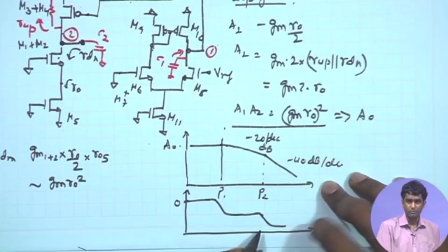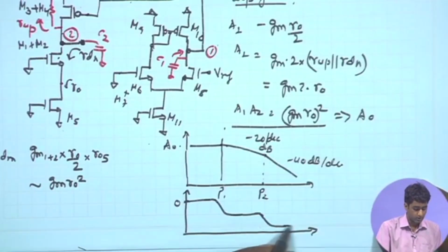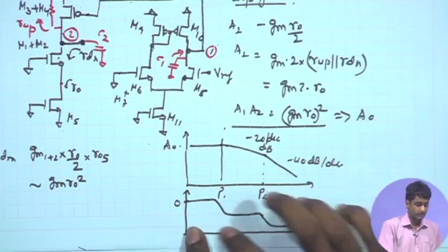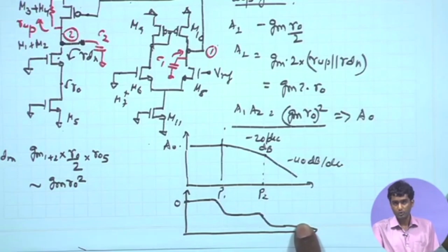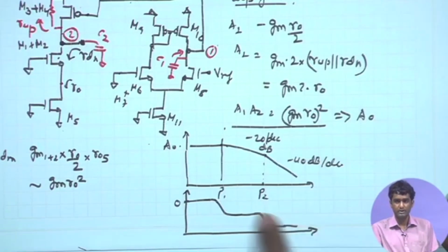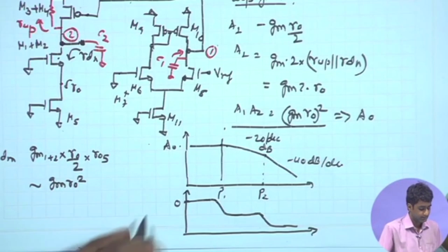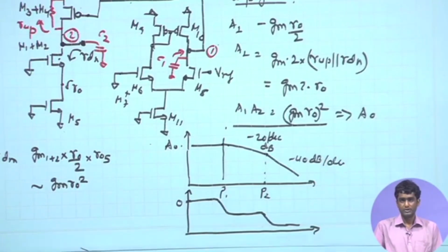So, depending upon how close is the third pole. If you do not have the third pole, we know that it will asymptotically reach 180 degree at very high frequency. If you have a third pole lying somewhere close, then it will quickly reach or touch 180 degree or go negative as well. So, this is the overall shape of the frequency response we expect.